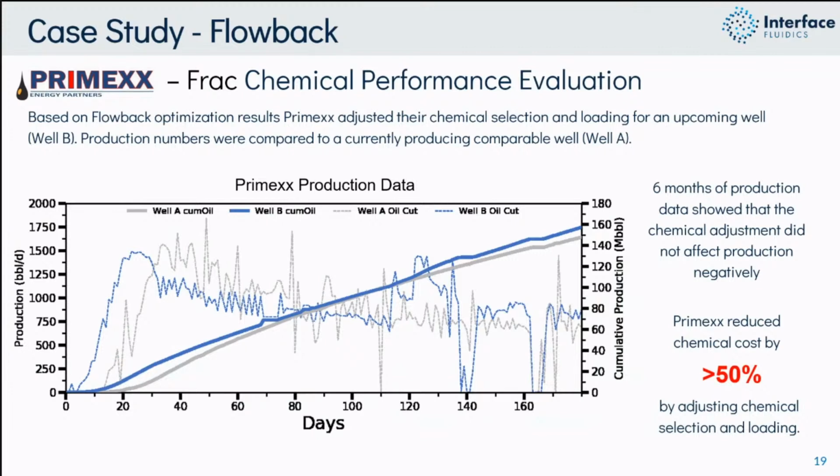The other thing that we see here, in terms of the peak of the production rate, is that the new well, which was completed with sample P4 at 0.5 GPT, reached the maximum production rate at around 20 days of operations or flowback, while for the older well we see around 35 to 40 days. So that could be another indication that this chemistry can have an impact on faster oil flowback compared to the other well, which was completed with the other chemistry.